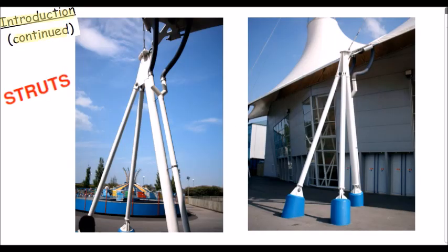Here are structural members. These are actually circular sections shown here in the photograph. And if loaded in compression, they could in theory buckle to this kind of shape here. So in this particular situation, they'll be checked for strength to ensure that the axial stresses are not excessive, that they don't reach the yield point. They may well be checked for stiffness and the deflections that occur due to loading applied. And lastly, they could be checked for stability to make sure they don't buckle if the load applied is compressive.